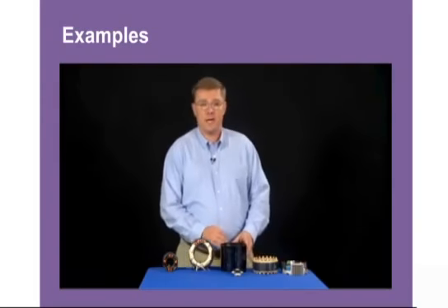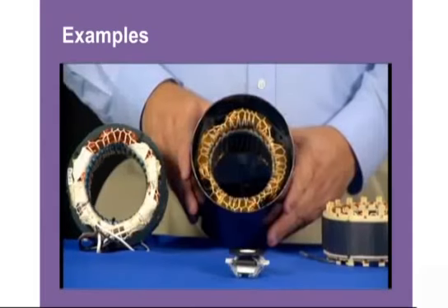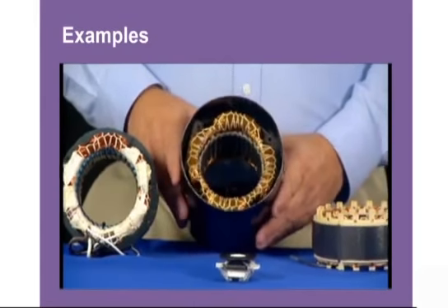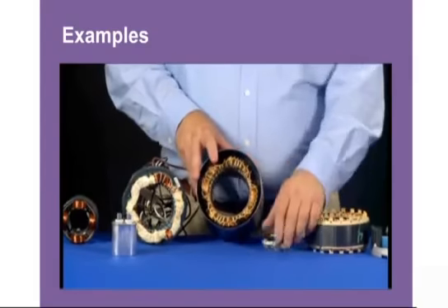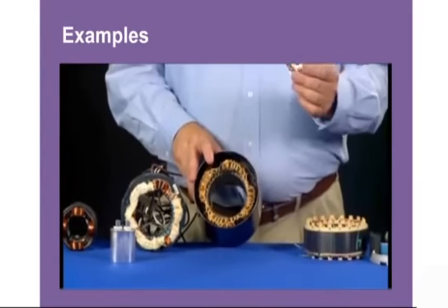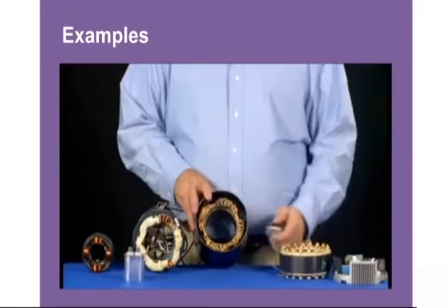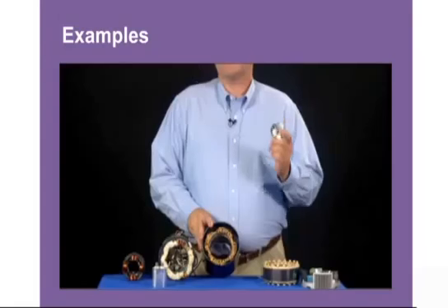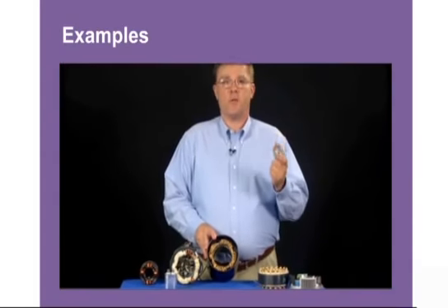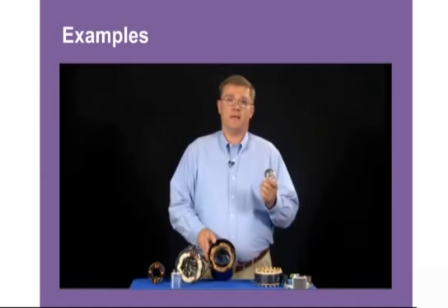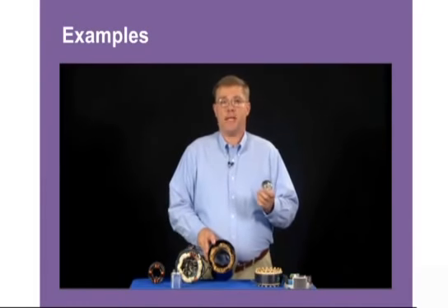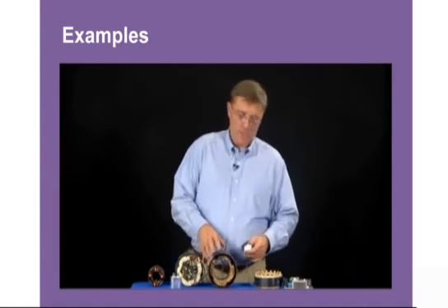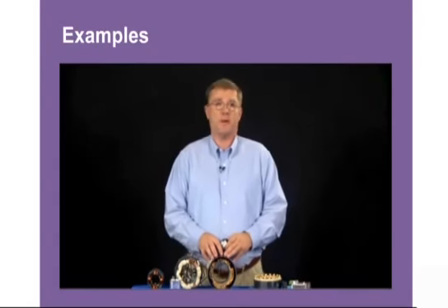The next type of motor we talk about are split phase motors. This type of motor also has 2 windings in it, an auxiliary start winding and a run winding. But what makes split phase motors unique is a centrifugal switch. This switch allows the motor to start on the auxiliary winding, which you'll note is a very fine gauge wire. It's designed to slowly come up to speed, and since centrifugal force opens the switch and allows it to go to the run winding, this motor's typical belt drive application allows it not to take off immediately and throw the belt off the line. There are three types of split phase motors.